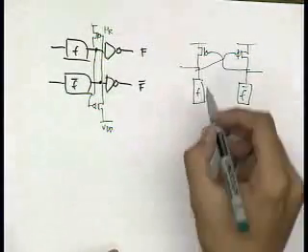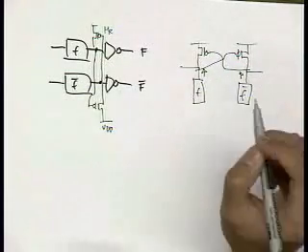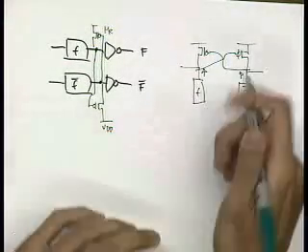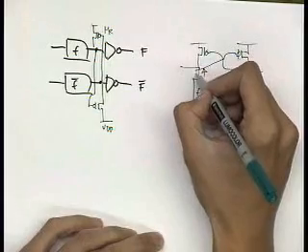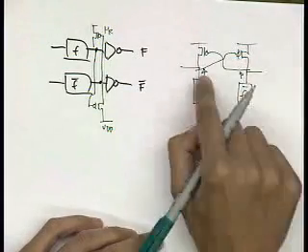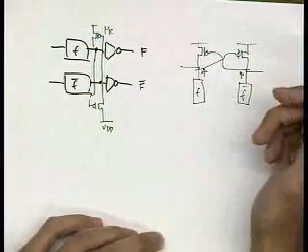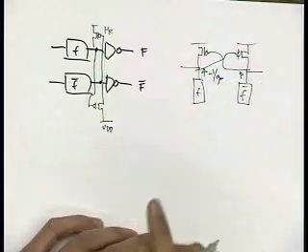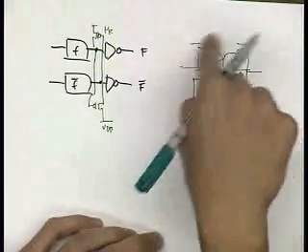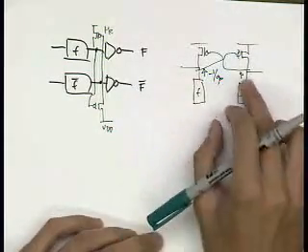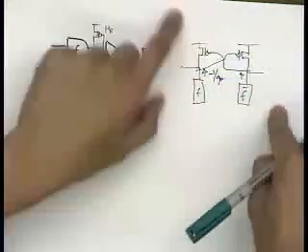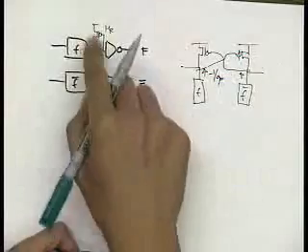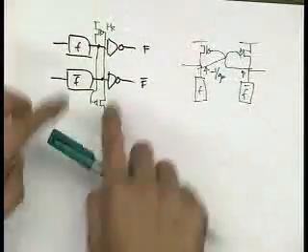If you look at the impedance looking up, if you solve this small signal, what happens if this changes by a small amount? If you have small changes here, you can approximately use small signal analysis, and those in 140 will see that this is actually a negative 1/gm impedance looking up because it has positive feedback. So small changes here will actually rail these two outputs. So that's one good use of using complementary things. You get that positive feedback effect.